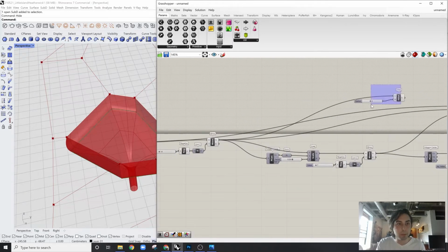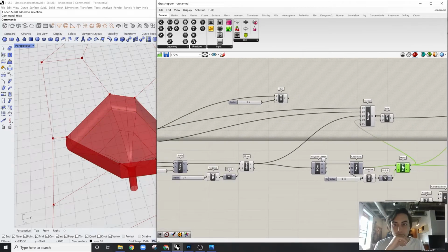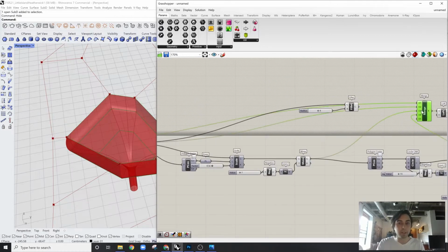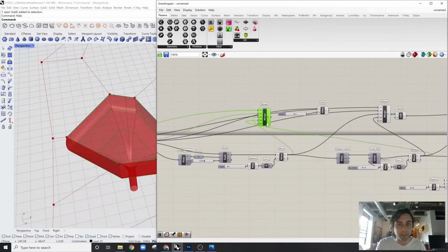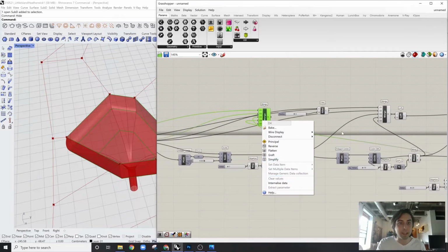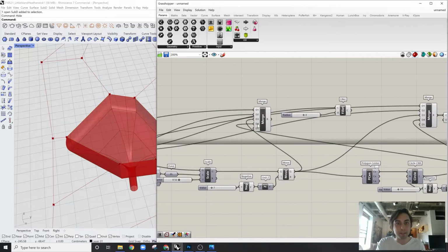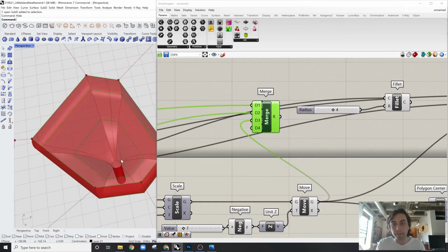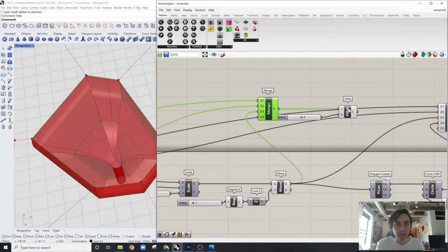Give it a really gentle fillet. So what I'm going to do is, I'm going to copy this merge. This is kind of a weird way to use merge, but I don't want to use that same, I don't want to copy. I could copy this fillet and just bring in all 3 of those different wires. But instead I'm just going to nix out the circle, because I'm not going to fillet, obviously, the circle. So I'm going to bring all of these guys into here.